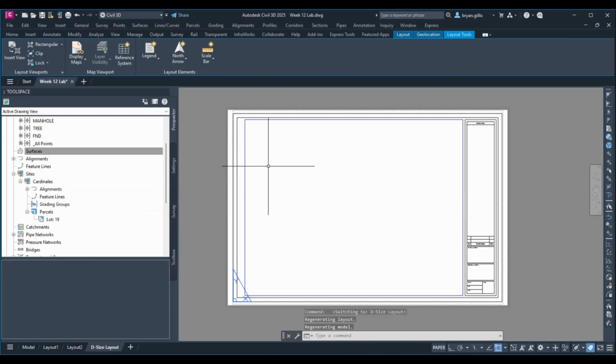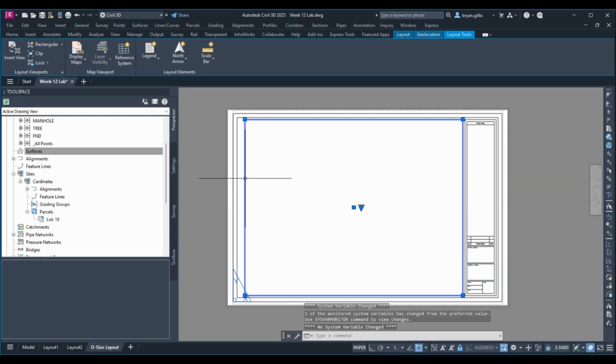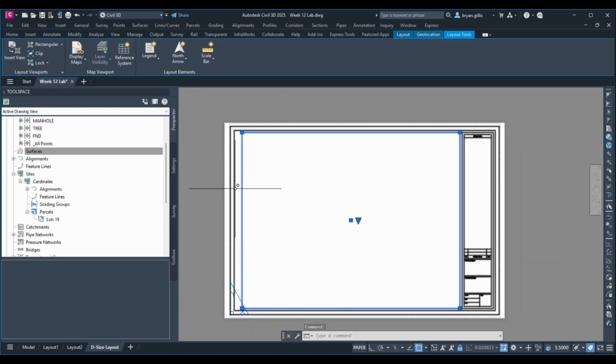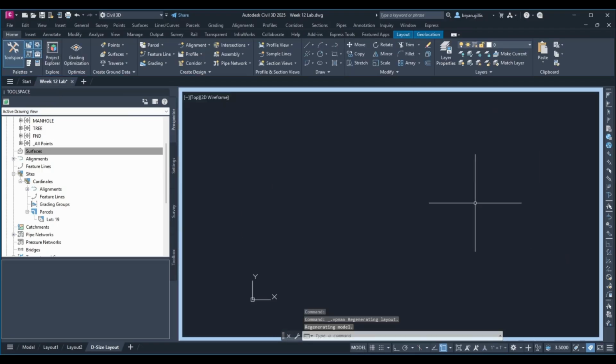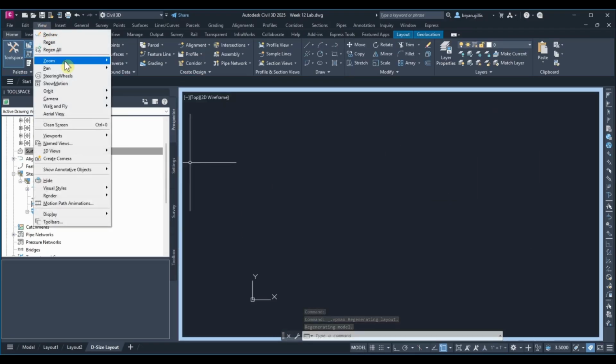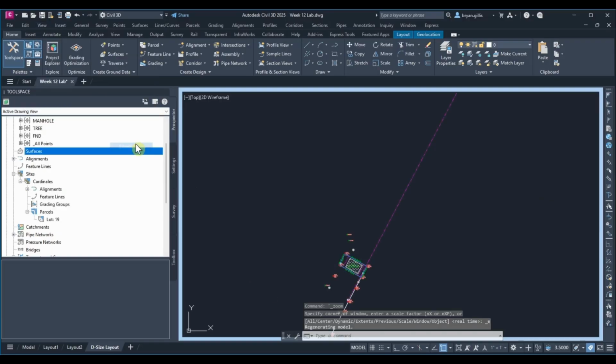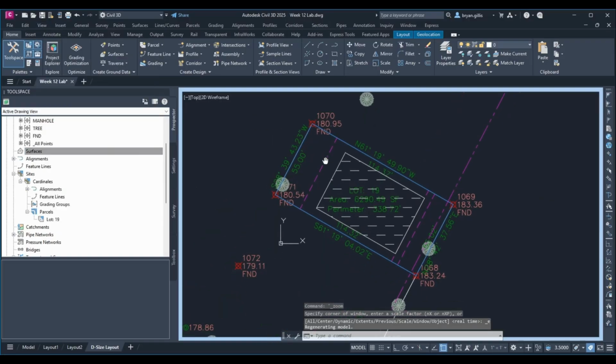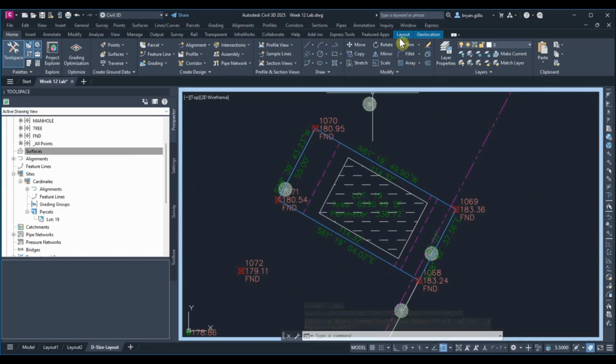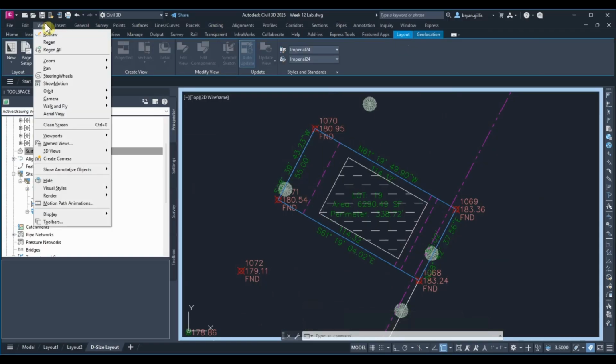So here's our template. First thing we need to do now is get inside of our viewport. We need to activate it. For those of you with GIS experience, the viewport is similar to your map frame. So first thing we got to do is we need to unlock it. So click unlock, then click on it, and then you can double click it. Depending on your settings, it's either going to open this max view or just turn on the frame. Go ahead and zoom to the extent of your drawing once your viewport is active. Let's get relatively centered on that. If you're in the max view, go ahead and under the view drop-down menu, go to viewports and set this to viewport 1.